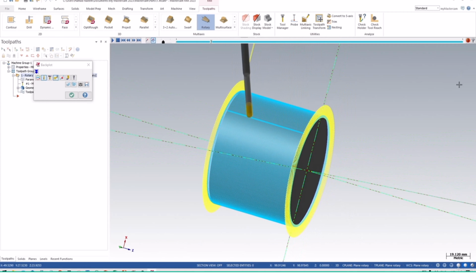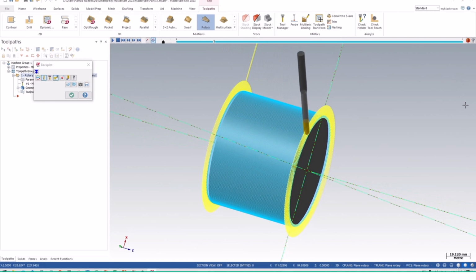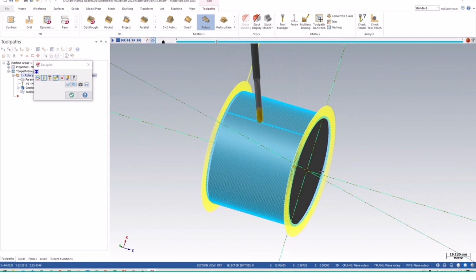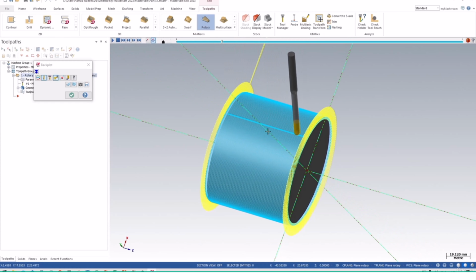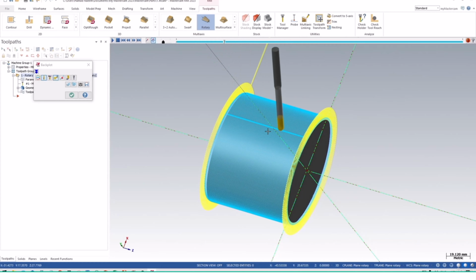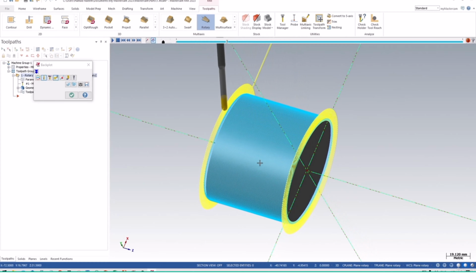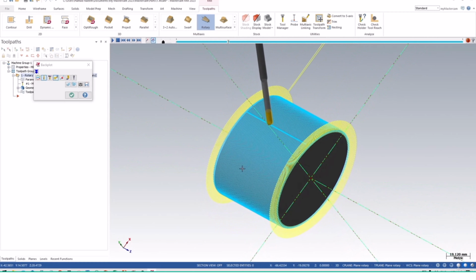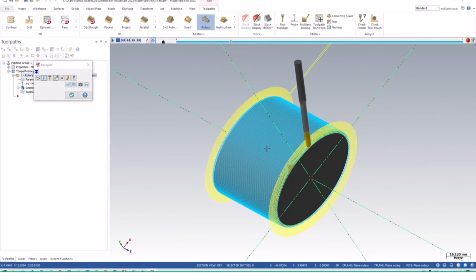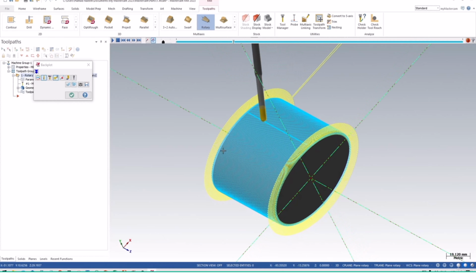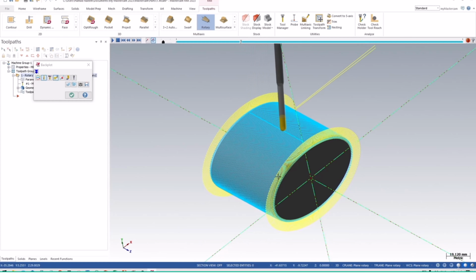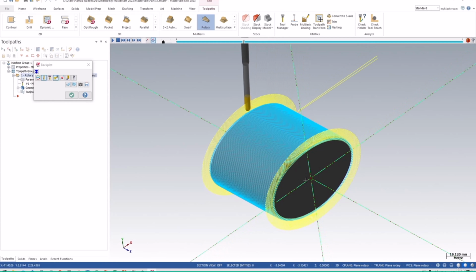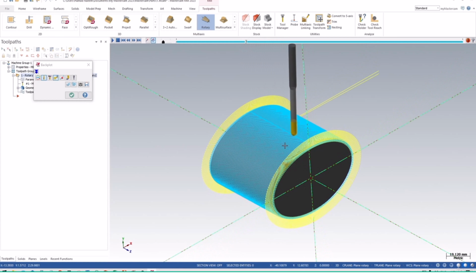So you need to select the appropriate setting for rotary positioning. Either you select the cutting method of axial cut or the rotary cut, but definitely it depends upon the profile or the geometry. I have generated a geometry which is compatible with both the rotary and the axial cut.